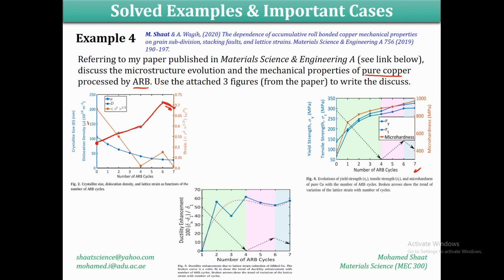And as we further apply plastic deformation by rolling over these subdivided grains, this will further multiply the dislocation density inside the material microstructure. Again, something you should understand, that I have mentioned in the video today, is that any material will reach a saturation state of its dislocation density. As I mentioned, after the first cycle, and this is what we are expecting for any conventional material, the dislocation will be significantly increased. After the second one it will increase until it reaches the saturation case.